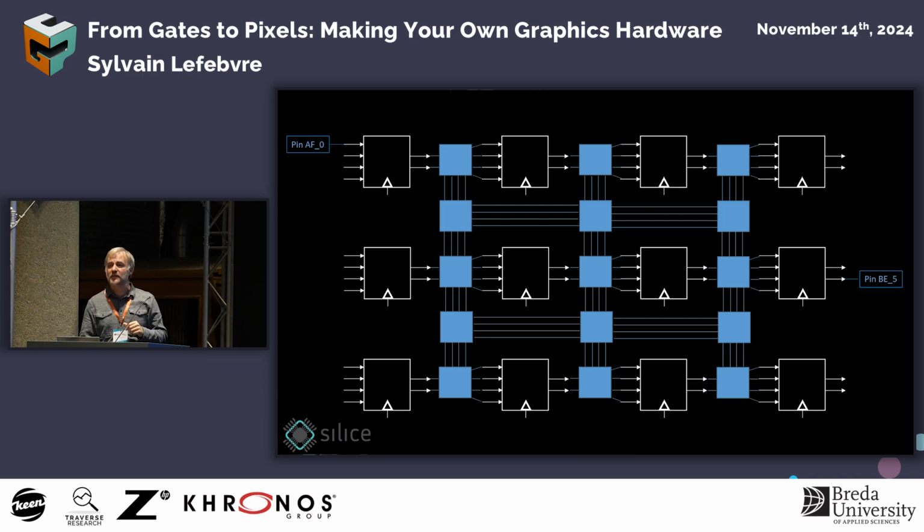And in between the routes, you have switch boxes that you can also configure to create routes between the cells. That's how you're describing the wires of the circuits you're trying to do. All right, and so now that you can configure both the gates and the wiring, you can implement your own hardware on the FPGA, and the FPGA truly runs and becomes this piece of hardware that you have described, of course with some overheads, because it takes time to do this lookup in each of the cells.